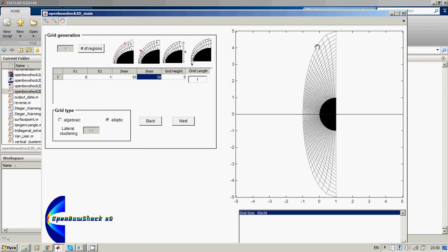On the other hand, if you make it such that it includes too many points, I'm not sure, but the code may give you some incorrect answers. If it's say 3-4 points out of 80 from each side, it's not a big deal at all. So always make sure you are far enough to ensure shock capturing.